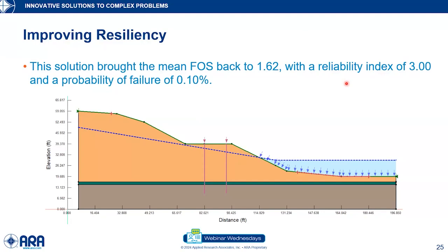Again, related to the actual case study, there was an evident movement of that slope over time, and there were serviceability issues noticed, and that reflects basically the reduced factor of safety. So that's another aspect: sometimes reduced factors of safety can lead eventually to a total failure, but it could also be an indication of a progressive failure leading to serviceability issues early on in the asset life, and then leading to potential total failure.